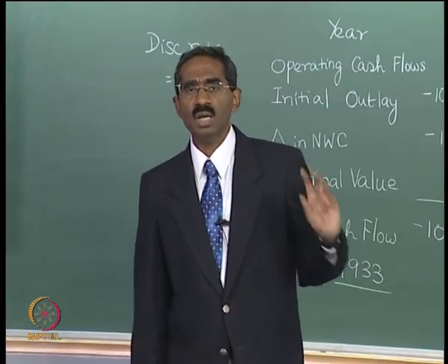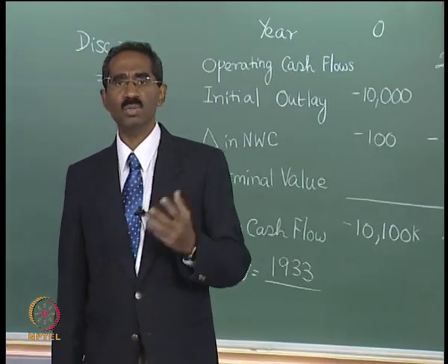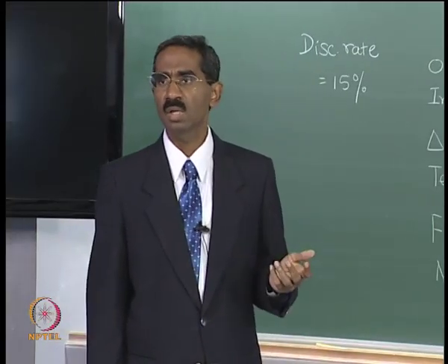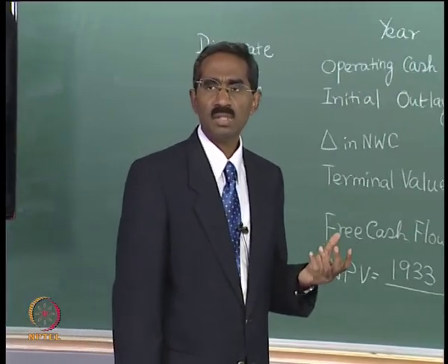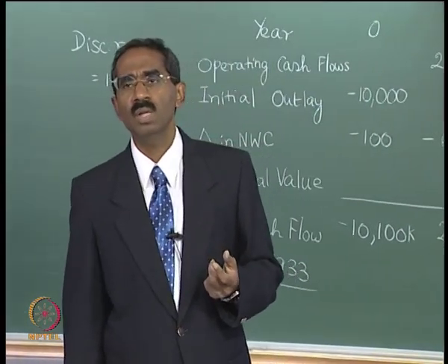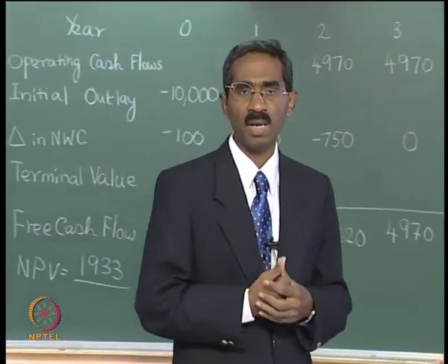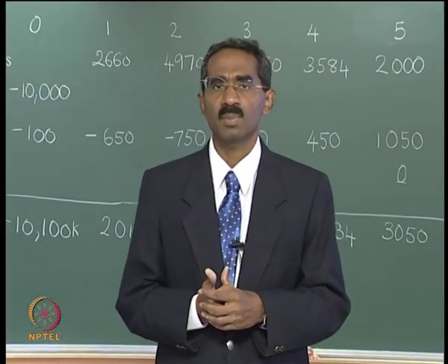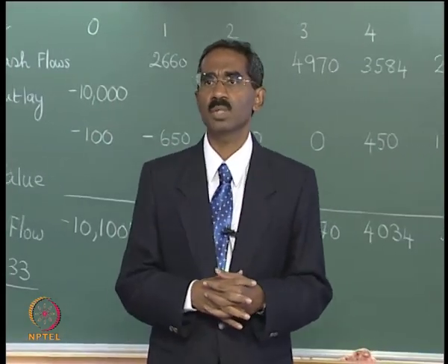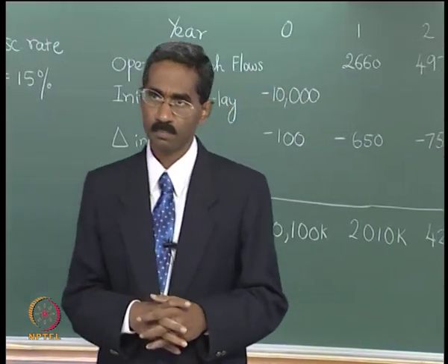And then we also have the fuel, and the cost of the fuel is determined by the amount of fuel that is needed multiplied by the price of fuel. So in this case, the natural gas requirement is 1950 million British thermal unit per hour. So that is the fuel that is needed if the plant is going to be functioning at 100% capacity, and the total fuel requirement per year is going to be 17082 billion British thermal unit.